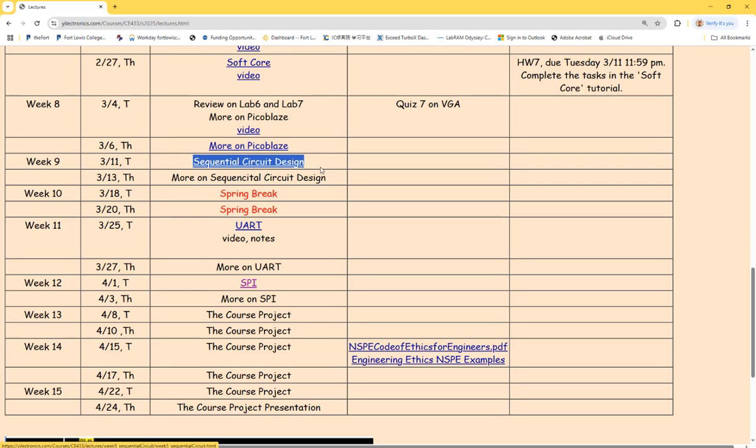I may want to remove this one. I don't know. I'll make it easier. So I'll let you guys go through the necessary ones as soon as possible. So at least we will be able to either use UART or SPI. So we are not expecting I2C. The I2C is really easy to use, but all the Verilog code behind the scenes is very complicated, like 5 pages or so of Verilog. So I think it's okay to use UART, just Rx and Tx, and SPI. They're easier protocols, but not as reliable as I2C.